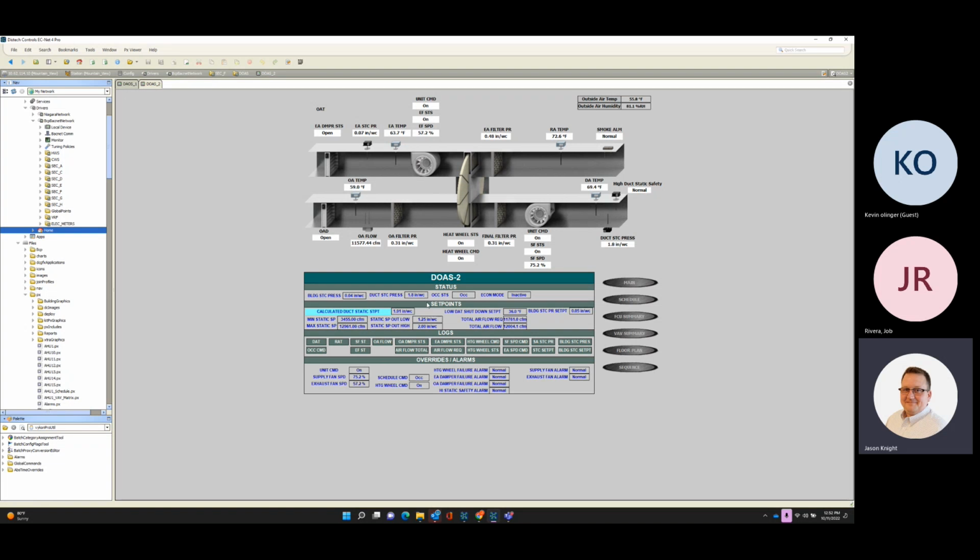So it slowed the fan down just a little bit too much. We're only making 1.8. So it'll speed it back up now to 1.91, or try and get as close as it can to that. So it's only making exactly what it needs. And this is only for fresh air. It doesn't heat it, doesn't cool it. It doesn't care about any of that. It just wants to make it.